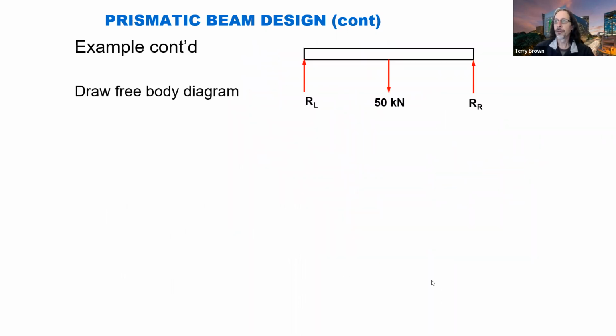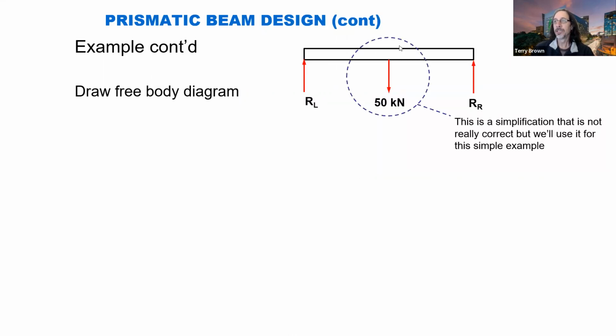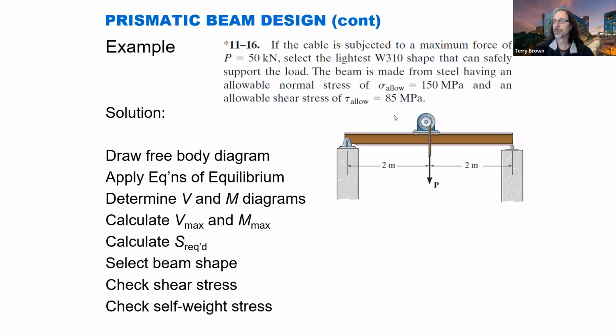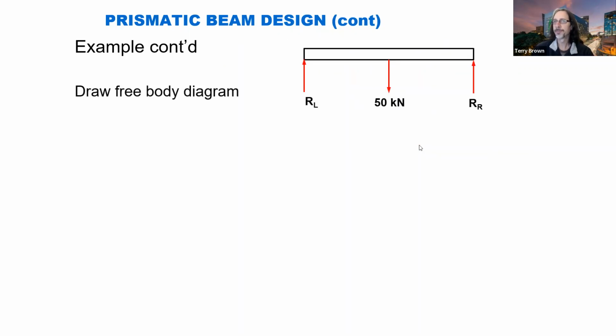All right, so drawing our free body diagram, pretty simple one in this case, so I don't have to spend too long on it. The other thing to note is this is a bit of a simplification, obviously, having a point load here. If we go back to our actual diagram, we've got this motor supported at 2 bolts. So there's the distributed load underneath here, there's bolt loads, etc. A little bit more complicated than I've shown in this simplification, but we'll just work with that for now.